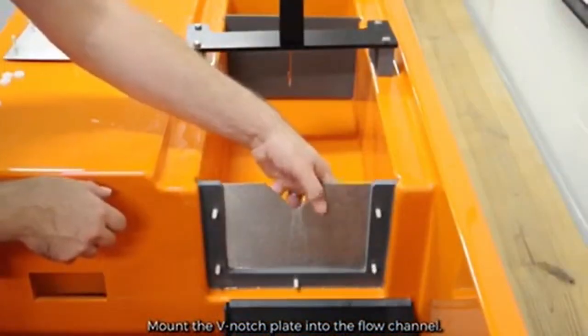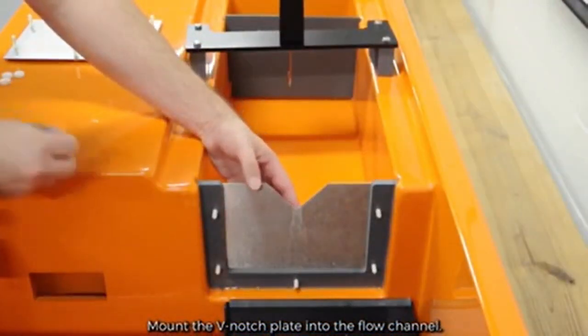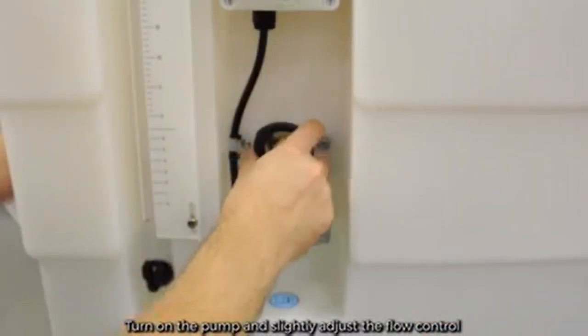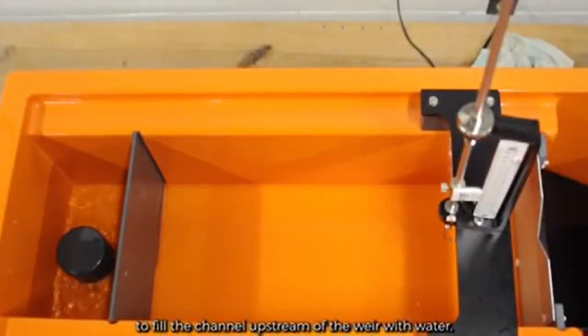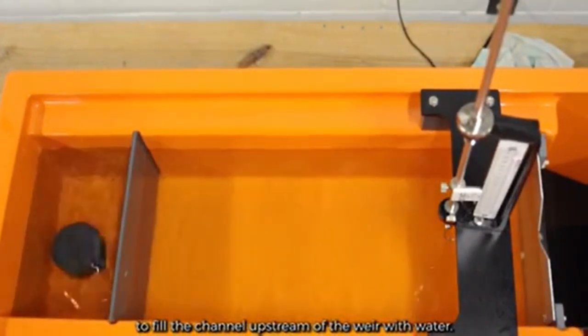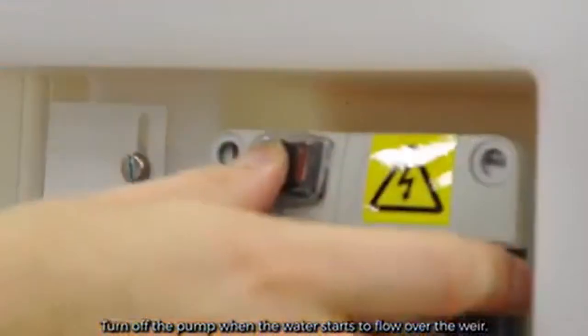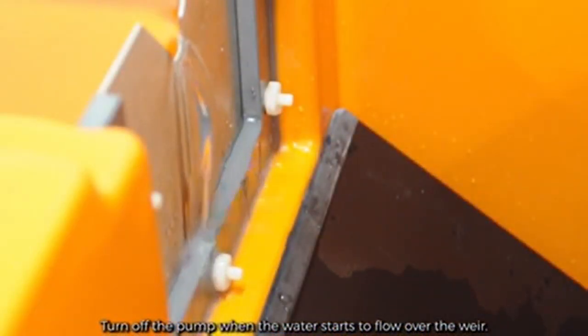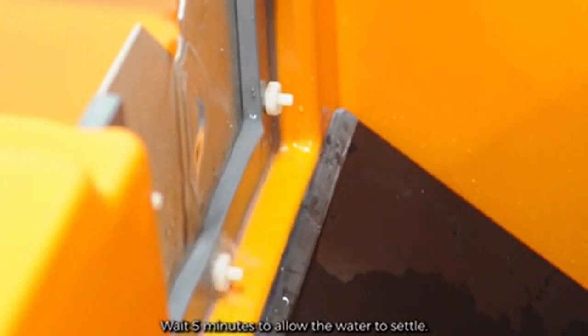Mount the V-notch weir plate into the flow channel. Turn on the pump and slightly adjust the flow control to fill the channel upstream of the weir with water. Turn off the pump when the water starts to flow over the weir. Wait 5 minutes to allow the water to settle.